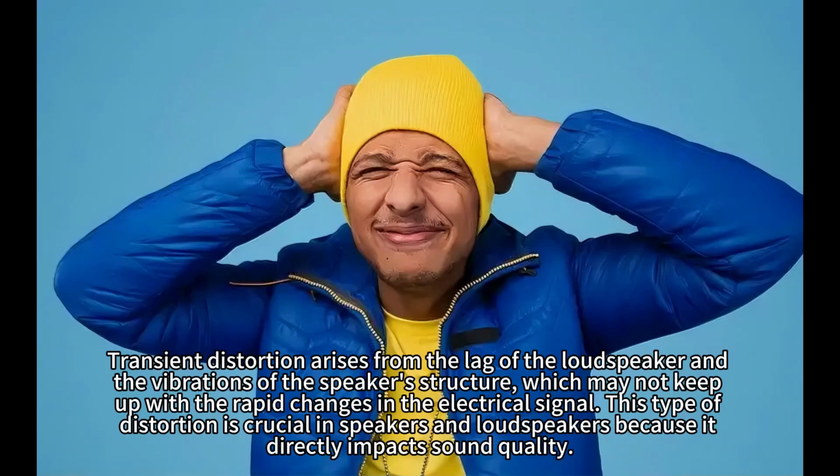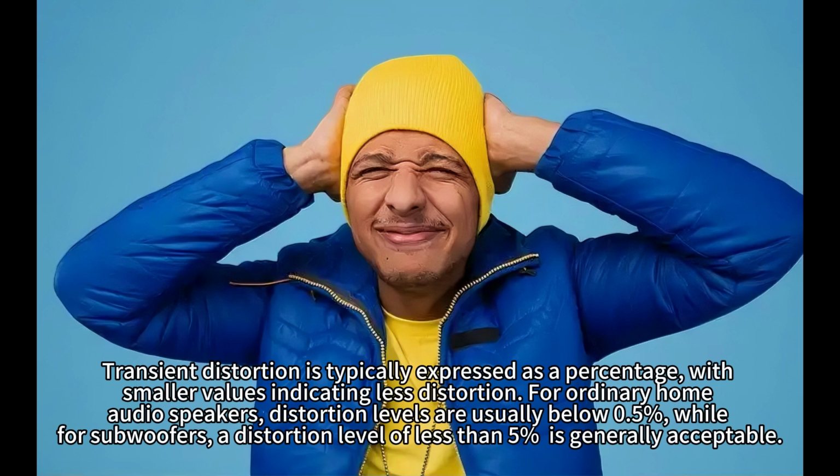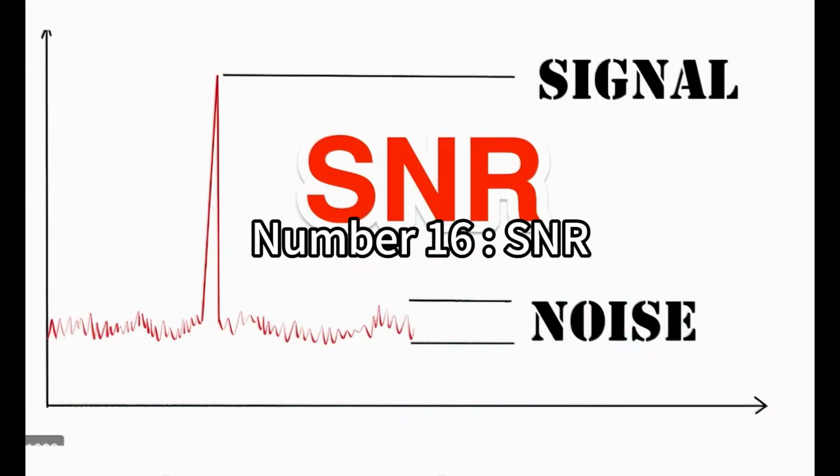Transient distortion arises from the lag of the loudspeaker and the vibrations of the speaker's structure, which may not keep up with the rapid changes in the electrical signal. This type of distortion is crucial in speakers and loudspeakers because it directly impacts sound quality. Transient distortion is typically expressed as a percentage, with smaller values indicating less distortion. For ordinary home audio speakers, distortion levels are usually below 0.5%, while for subwoofers, a distortion level of less than 5% is generally acceptable.